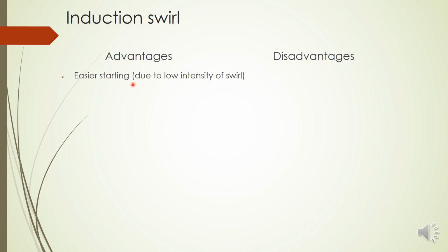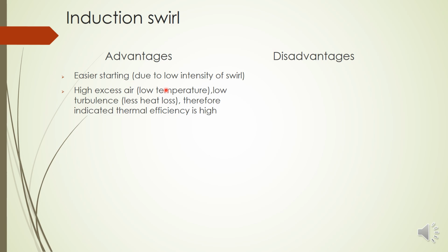So cold starting problems are less. Then there is high excess air due to low temperature and low turbulence, which results in less heat loss, and therefore indicated thermal efficiency is high. Due to less heat loss, indicated thermal efficiency will be high in this type of swirl.